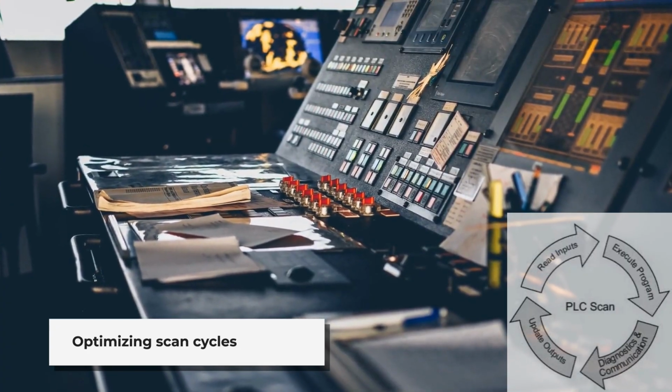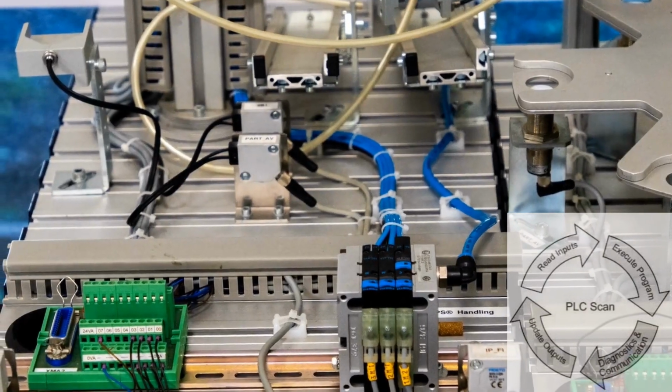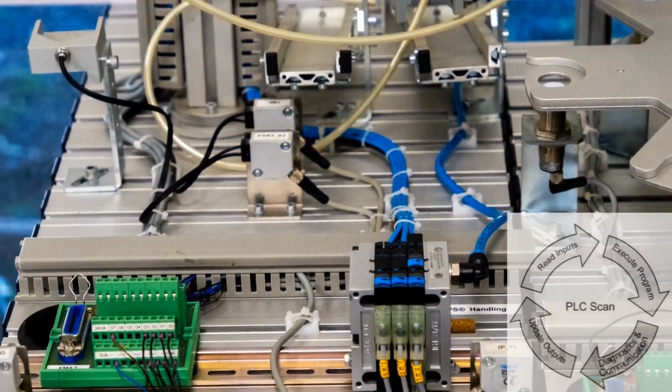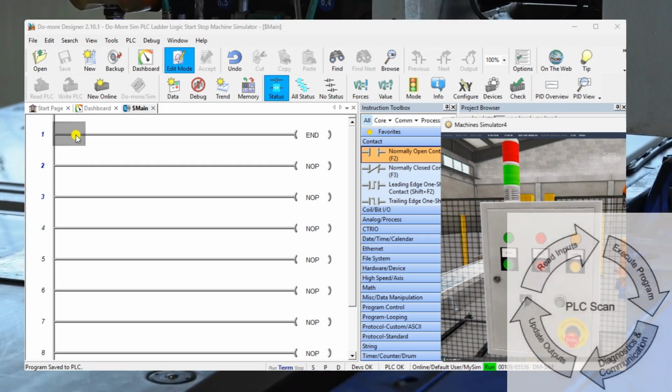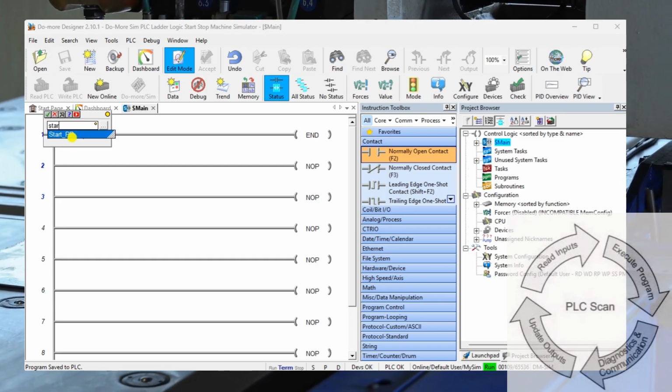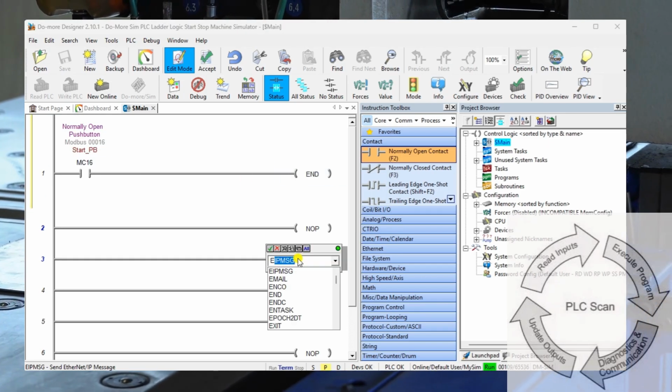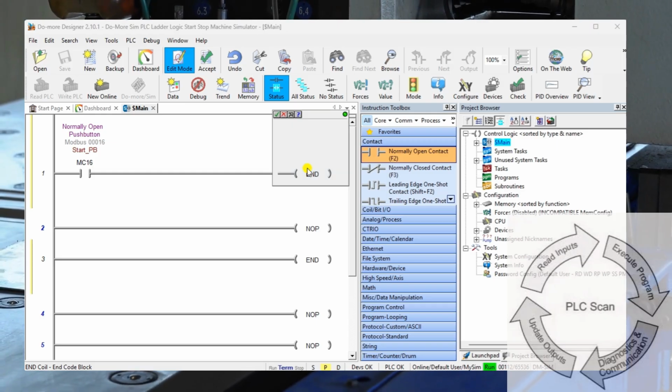the automation system. The PLC reads all inputs before executing the program logic and then updates all outputs after the logic is complete. The order of instructions within the program itself can affect the internal logic, but the physical I/O is handled in a set sequence during each scan.